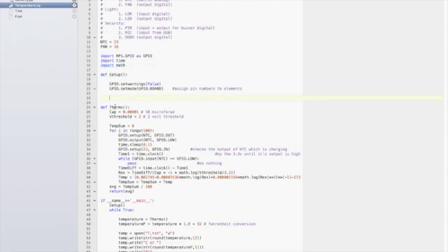Now we're moving to the thermal function. The thermal sensor that we are using is the NTC, and it's not linear, so it's not digital either. The GPIO pins are all digital. We can't detect something that's analog from them. We can't use it. We need an analog to digital converter.